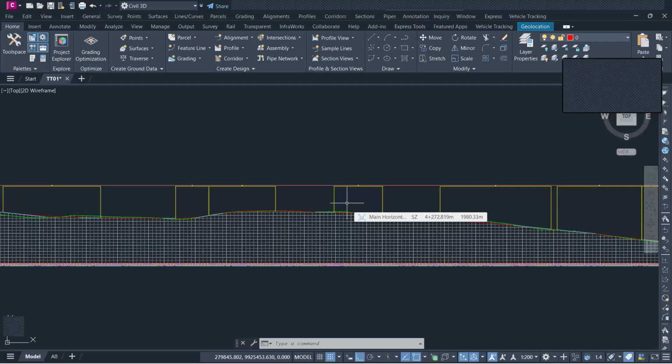So if they don't meet the requirement for different classifications of traffic, of course, you can look at, for example, RDM Part 3 or AASHTO 1993 for road materials, and you will have a deeper understanding of the classifications that we have for various subgrade materials as related to various traffic classes or loading. So if this material does not meet this minimum requirement, that is when you now cut to spoil. An obvious example is when you find there is a lot of cotton soil within your alignment. So that material is cut to spoil. You cut and go and dump it away in another place.